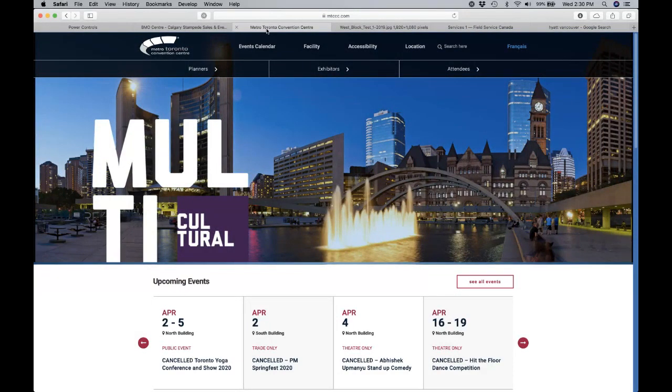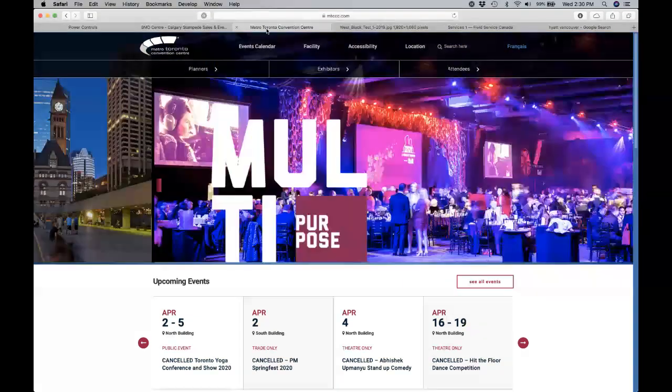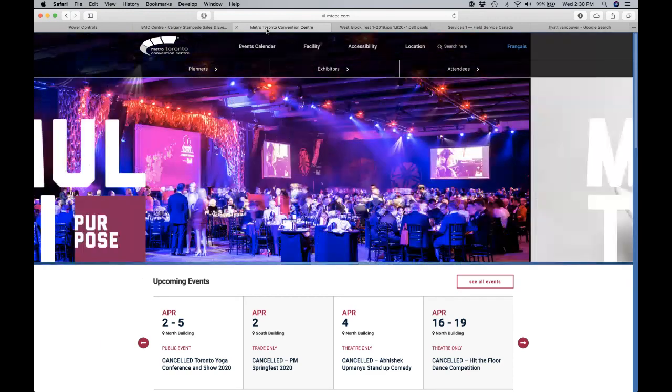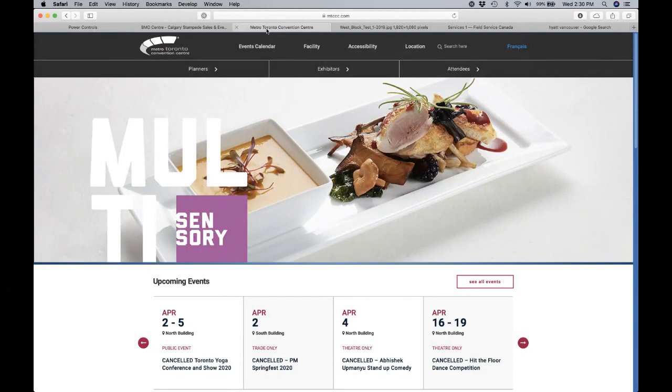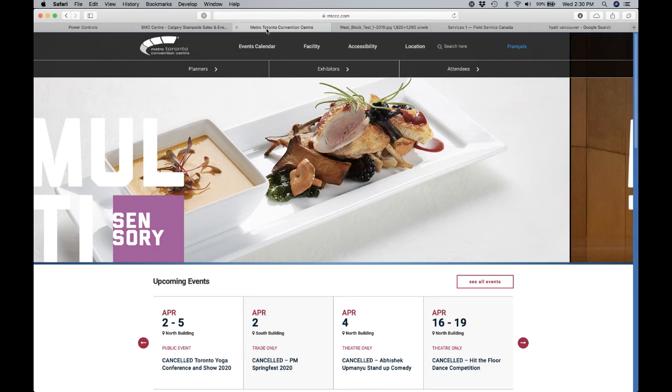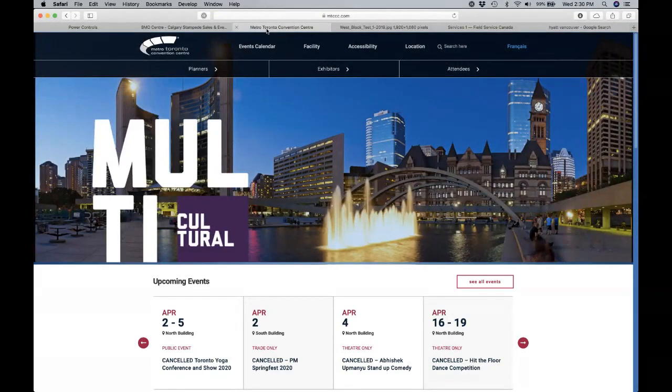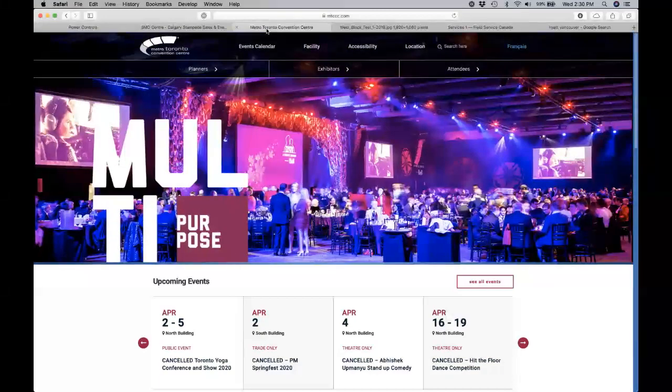in both the facilities management and the security offices that allow those different players and stakeholders in the building to be able to monitor not only the lighting status, but they're actually looking for occupancy state in all of the breakout rooms, as well as being able to provide that information to the HVAC system, where we're giving integrated information over to the air handling system. If there's occupancy in a room, they are turning on the cooling. If it's in the schedule for the room to be used, we're getting information back from the BACnet system to be able to enable the lighting or change the sensor statuses in the rooms.